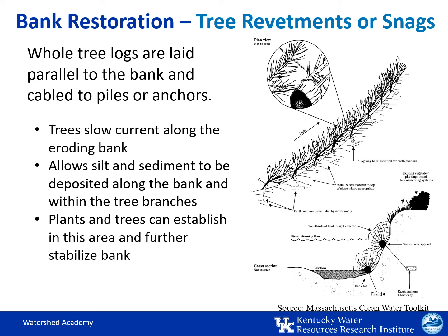The deposited material then becomes a good seed bed in which river trees such as sycamores can sprout and grow. The resulting trees spread roots throughout the revetment of the stream bank, and then by the time that these trees have decayed, the bank should be stabilized by the roots of the living trees. As an added benefit, these provide a lot of excellent fish and wildlife cover, so additional habitat while that process is occurring.